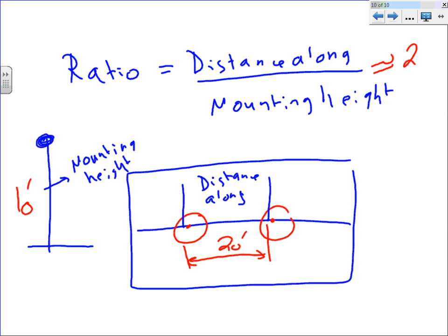So in this case, guys, if this is 20, what do you think this part here would be to give me a good distribution? This will be 10, and the last part from here to here would be 10. That's a 2 to 1. Typically, here's your parking lot, and between the two fixtures is 20. I want to make sure this is not further than 10 away from the other edge to cover that area.